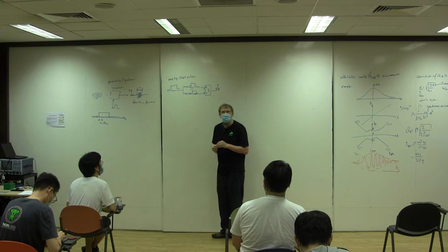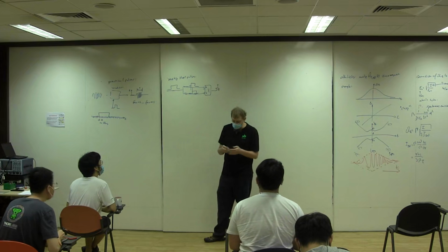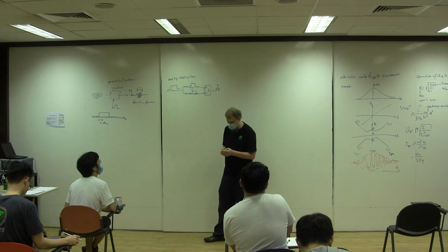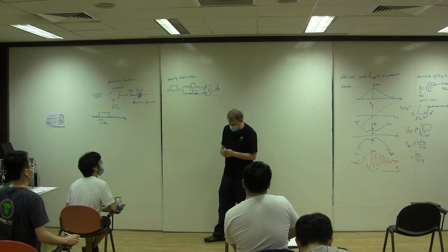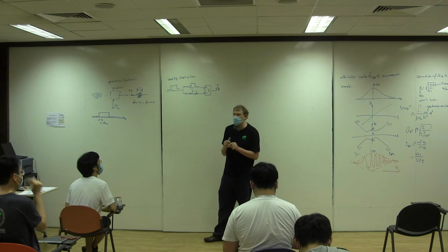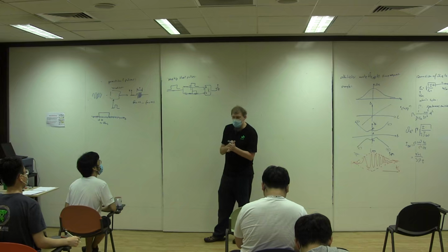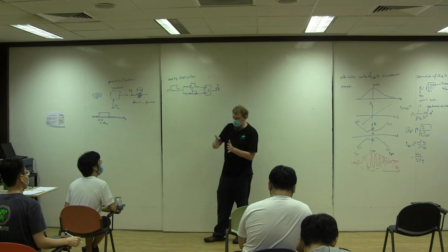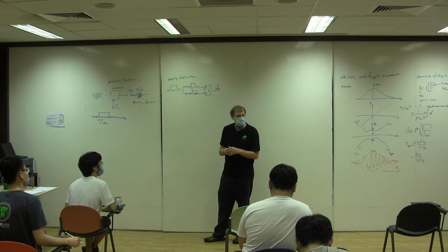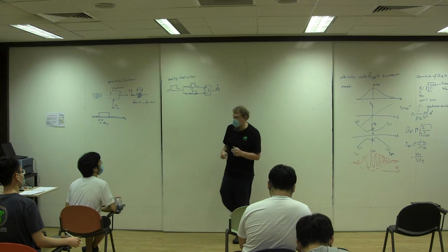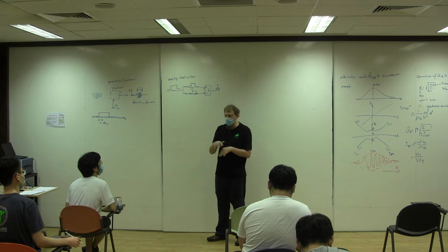You can also nowadays, if you program these FPGAs, use them for making such pulses. If you find that the device you chose is not fast enough, you often get devices that have blocks built in to make serial communication. For FPGAs, a typical timing slice is on the order of 10 nanoseconds, simply because the time it takes to go from one side of the chip to the other side of the chip is a few nanoseconds. And anything faster is difficult to implement in the standard way in FPGAs.